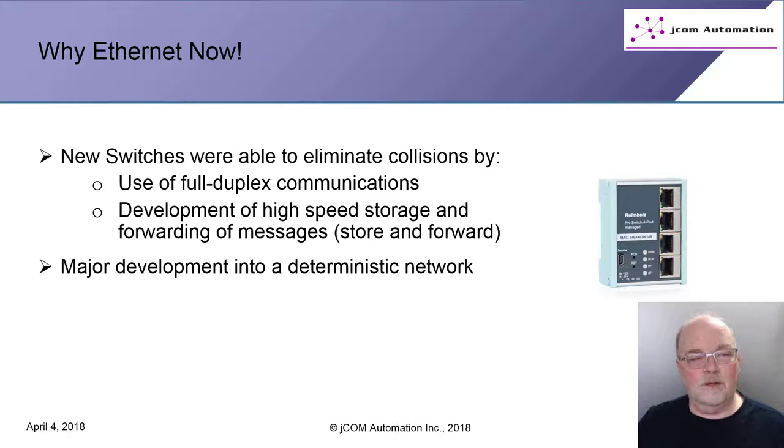If it's completely random, that just won't do. Long delays, you don't want to hit an e-stop and then sometimes it just takes 10 milliseconds for it to stop or to issue the command to stop. Sometimes it takes 5 seconds. No. We wouldn't want stuff like that. So we really needed determinism.